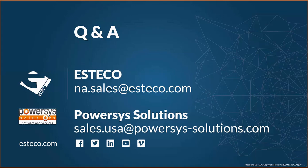In cases of nonlinear responses, as we had in this particular case, where the torque ripple is nonlinear, some of the RSMs may not do very well, so it becomes a little bit tricky in terms of what surrogate model you use for a surrogate model based optimization algorithm. So yes, we can certainly try other algorithms, but we honestly did not get a chance to run all of them. But that's certainly an approach that we can take in the future.